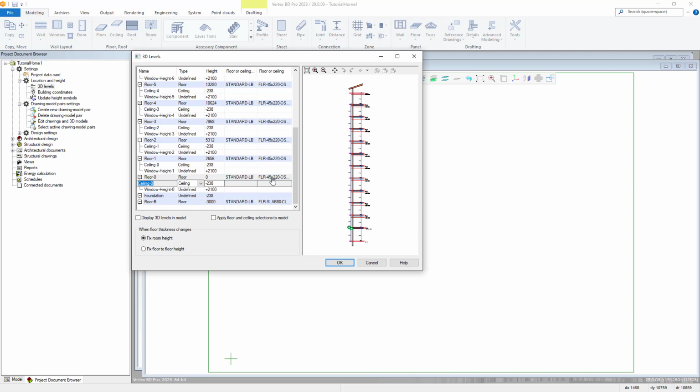When you add objects to your building, they are automatically constrained to a height level. By default, the bottom of the wall will be constrained to the active floor level, and the top will be constrained to the ceiling level above that floor. Objects like wall cabinets will be constrained by some distance from the ceiling level. If a height level is changed after you start modeling your building, then all of the objects that are constrained to that height level will adjust with it. This makes it easy to modify the building heights later on.